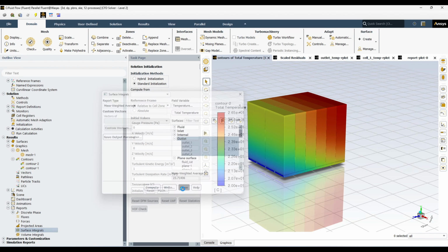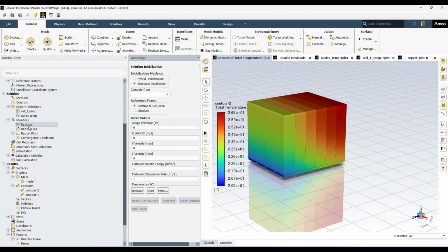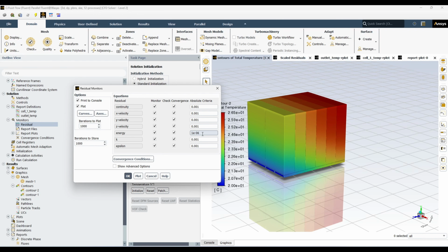If you remember at the start, when we were setting our simulation setup, I told you that residual should be -8 for temperature. If I would have used over here -8 or -9, we would get closer, but of course there will always be some numerical error.